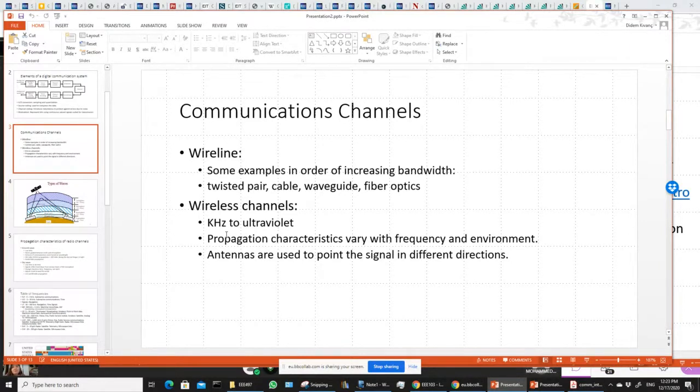And these can be very different depending on, for instance, the environment. Inside a city, there's lots of reflections. In a room, there are many objects. So the signal is reflecting, running into things, going through things. That's very different from transmitting in the middle of a suburban environment, in the middle of a field, right? And also, the propagation characteristics change, like how much signal you get and how much that signal varies in time. Because if you're in a place where there are fast-moving vehicles and things, your signal might be good one second and then it goes bad. So the gain changes a lot.